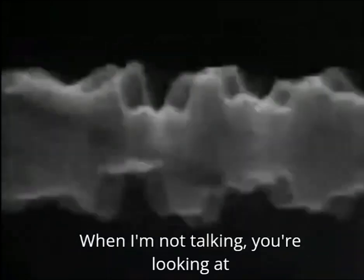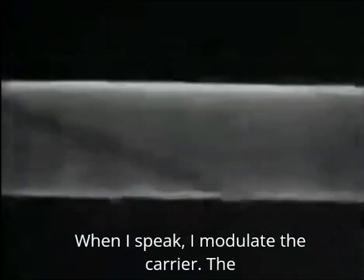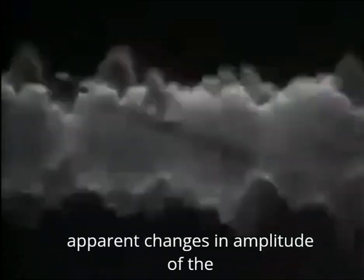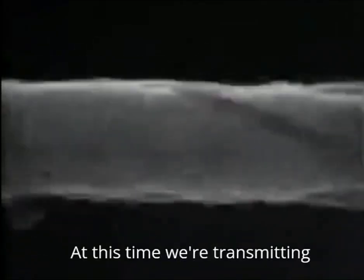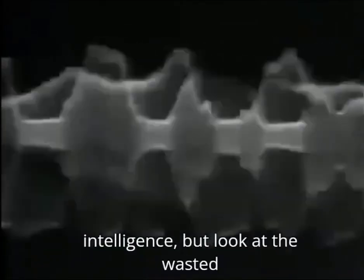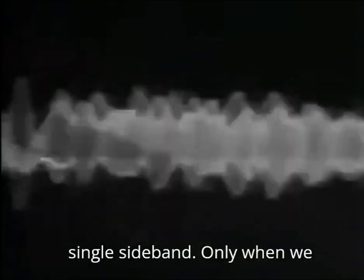When I'm not talking, you're looking at the RF carrier, wasted energy. When I speak, I modulate the carrier. The apparent changes in amplitude of the carrier are caused by the phase relationships of the sidebands generated. At this time, we're transmitting intelligence. But look at the wasted power in the carrier. Thus, the reason for single sideband.